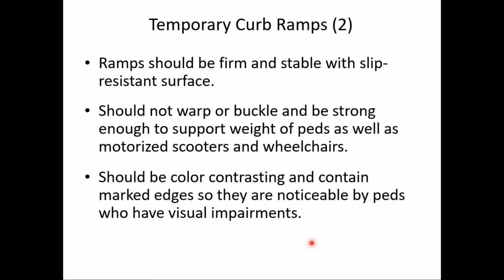Ramps, of course, should be firm, stable, slip resistant. They shouldn't warp or buckle under wheelchair use or other pedestrian use. And remember, it's not just manual wheelchairs, but they need to support the weight of motorized scooters and wheelchairs as well. And desirably, they should be color contrasting and have marked edges so that they are noticeable by pedestrians who have visual impairments.